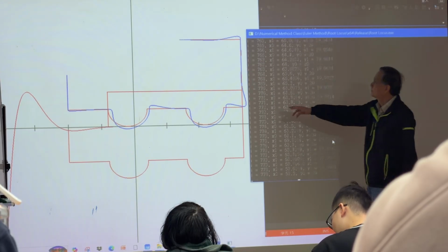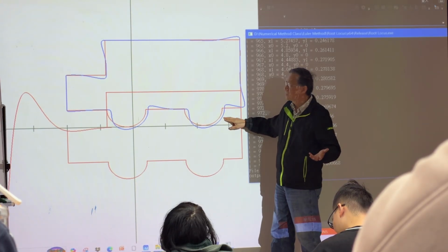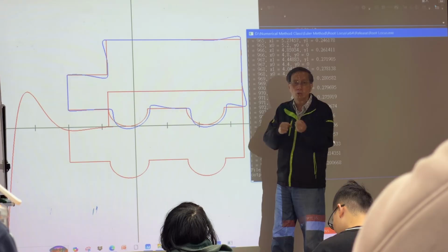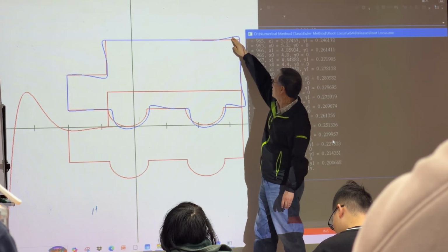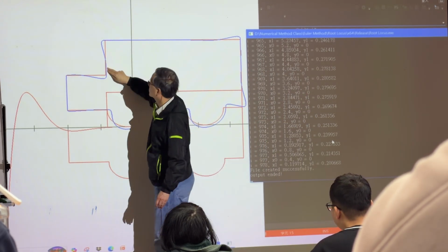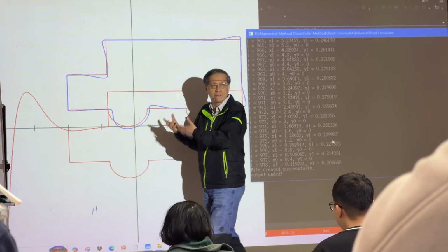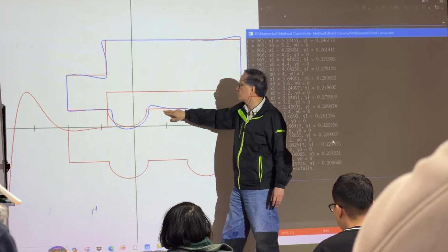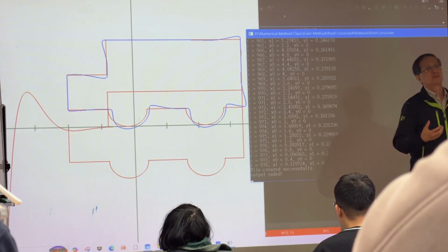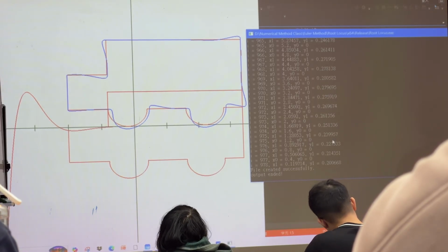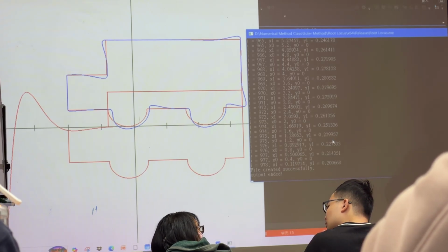You see here, the blue color, because of the dynamic delay, this time the x and y axes do not match well, and they do not follow the original path. It becomes like overshooting here. Here is overshooting. Here is also overshooting, and it comes back here because we have overshooting. Remember? So when we have faster speed, the machine accuracy becomes poor, the machining precision is reduced.